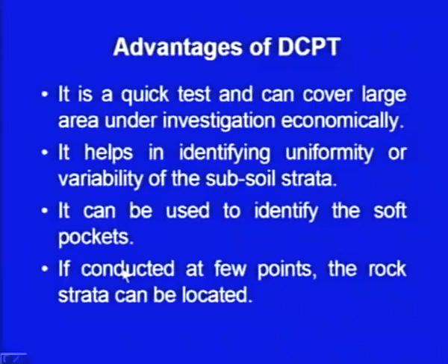There are certain places where rock is very close to ground, maybe 3 meter, 4 meter, 5 meter, and if you conduct it at few points, then you can locate the rock strata. Why I am saying few points is you should not derive this conclusion from one single test, because again the problem is we do not know whether it is a rock or it is a boulder or stone, due to which we got excessively large values.